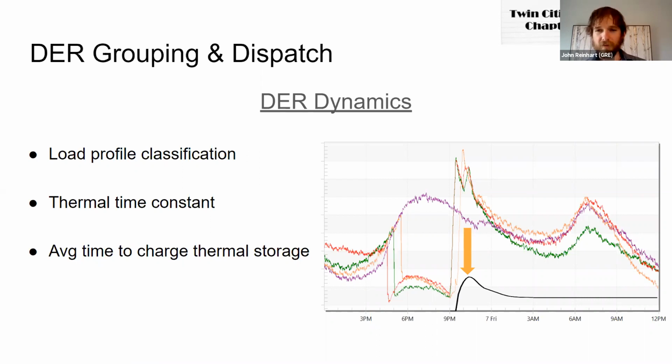And the pink curve shows what that load would have looked like otherwise. And if that load isn't restored in a graceful manner, you get a little bit of an overshoot, as an example, from some thermal loads. So you might want to know how much it's going to overshoot as a utility operator. I might want to know that, and how much time is it going to take before it settles back in.